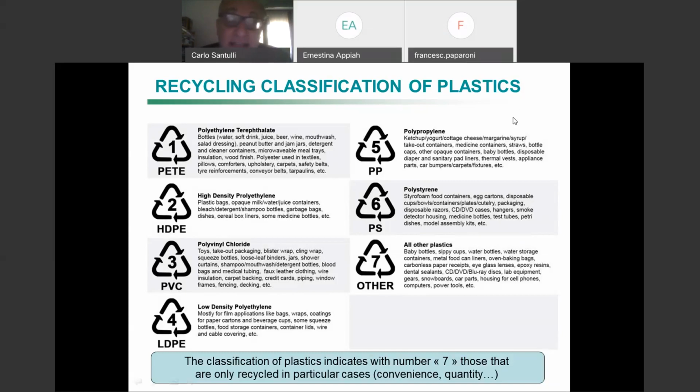Most light but resistant materials in car industry are made of polypropylene matrix and glass fiber. They use also carbon fibers in car industry, but not in the usual cars we use. In racing cars, yes, they use carbon fibers, but they are much more expensive and rigid. But they are able anyway to absorb a lot of energy, which is useful in case of accident.